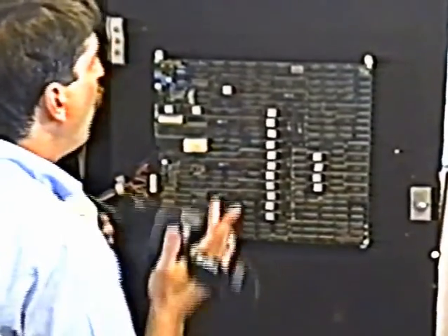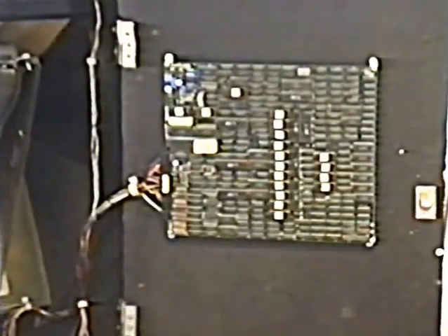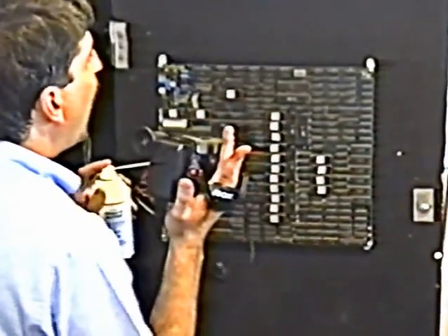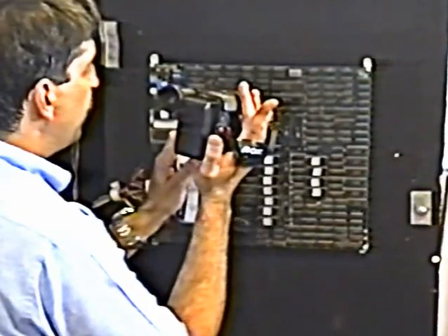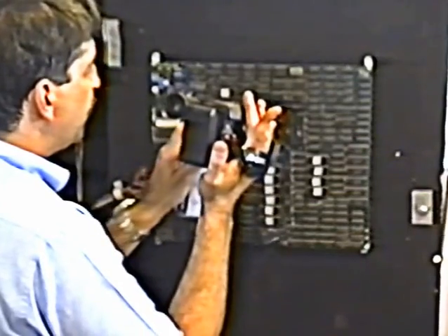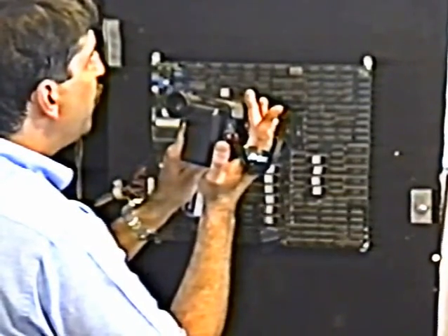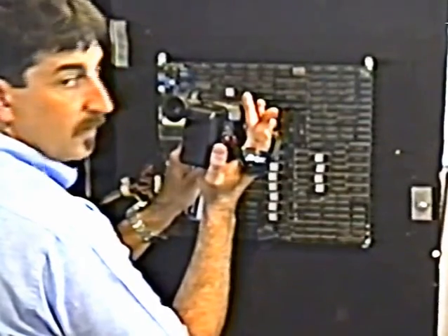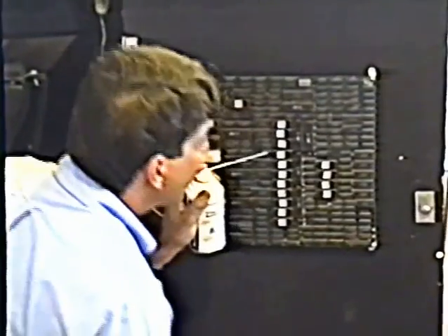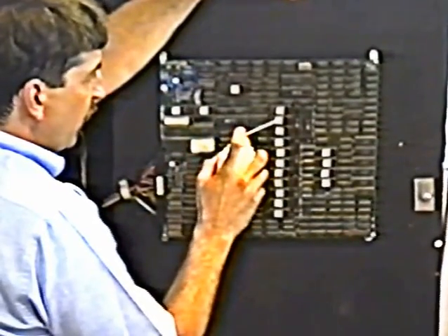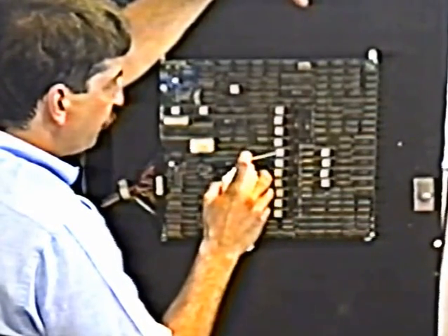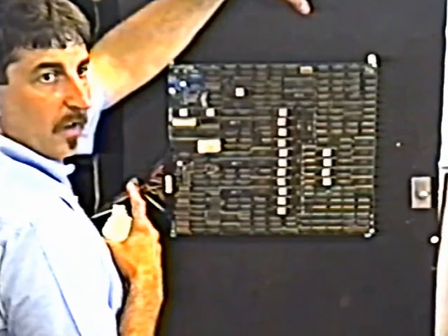Then, one at a time, you start freezing the chips. I always start with the big ICs. And you just drill, don't go like this. Just drill a little bit on it. When you get to the bad IC, the problem will go away. In other words, you hit the integrated circuit, you start hitting them one at a time. Let's see if that garbage on the screen only occurs when it's warm. You hit it, you freeze the chip, bingo, problem goes away.